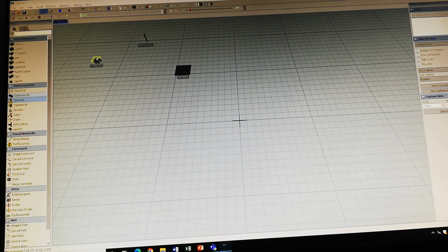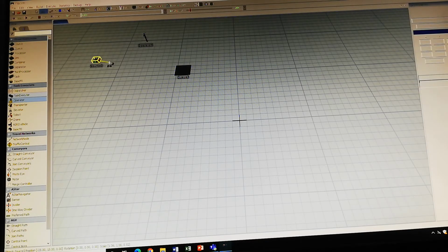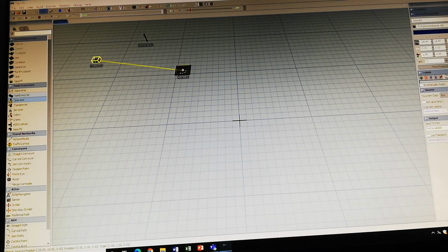So you are going to select from the source with the yellow window. You give one click and you continue with the click till Q, select Q, and you release the click. Press escape. With this you can see one arrow that is indicating the first movement to have.